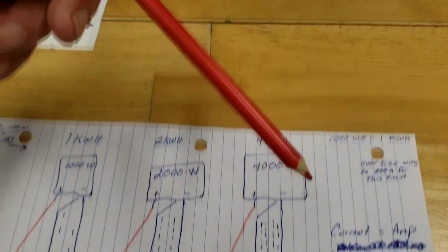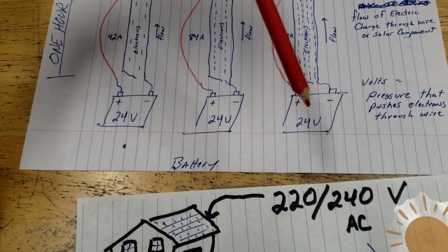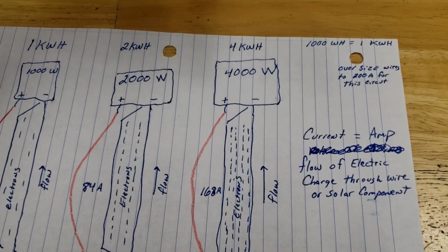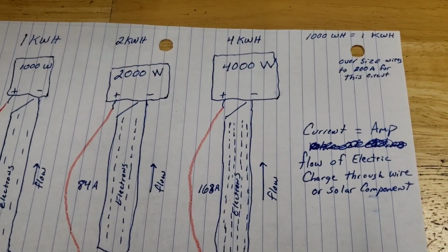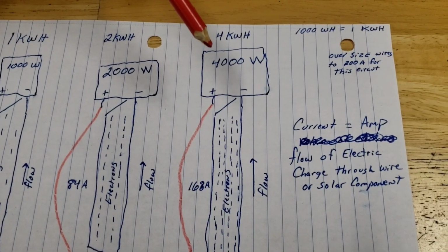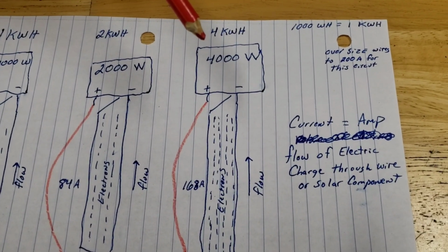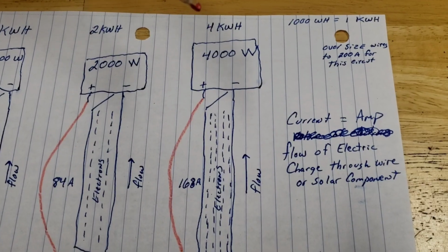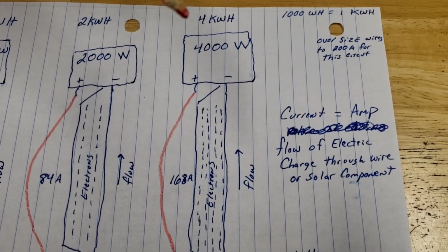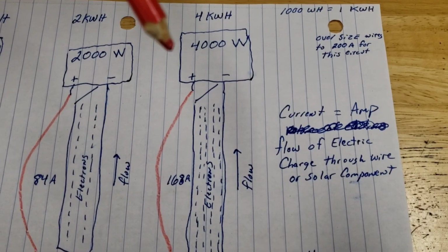All right, for my battery, for this spot down here, you want to use wire to the bus bars that can handle like double that kilowatt, that 4,000 watts. You want it to be able to handle like 8. If you double it, now there's more than enough room for the load you're going to be doing in there to travel through the wire and not make any heat.